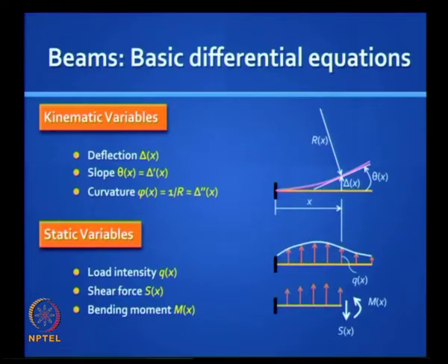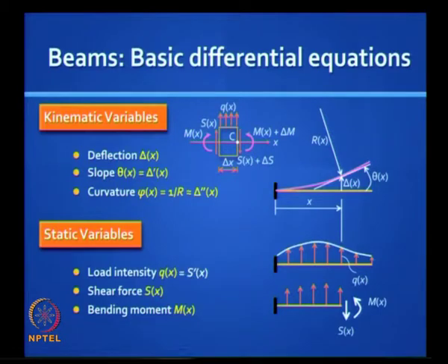Shear force is the derivative of... okay, so you can prove this by taking a small element of the beam and just applying direct equilibrium, and you can prove that the load intensity is equal to the derivative of the shear force. The shear force is the derivative of the bending moment, and what else can you prove? The bending moment is related to the kinematic variables how?